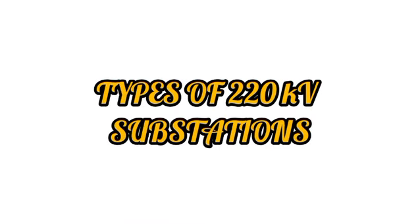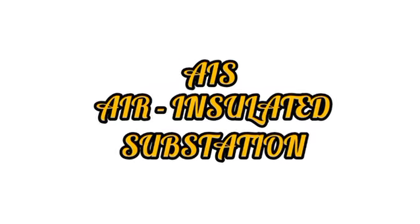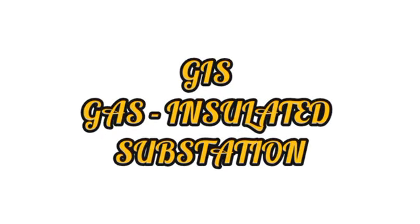Types of 220 kV substations. AIS, Air Insulated Substation. Equipment is installed outdoors and air is the primary insulation medium, easier to inspect and maintain, requires more space and is vulnerable to pollution and weather. GIS, Gas Insulated Substation.